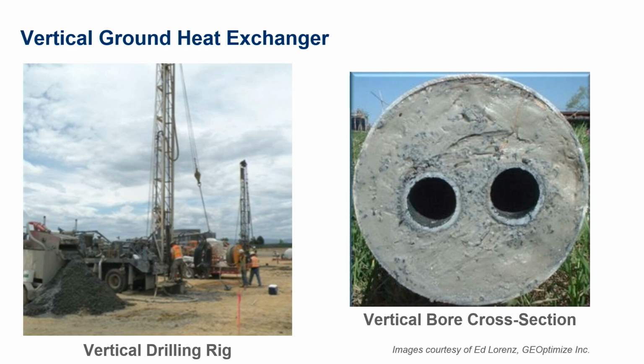The image on the right shows a cross-section of a borehole with grout filling the area around the supply and return pipes. Some drillers have low-profile rigs that can be used in an existing basement, and directional drilling can be used for vertical bores, allowing a large quantity of bores to be installed in a small surface footprint while fanning out underground to be in contact with a large volume of earth.